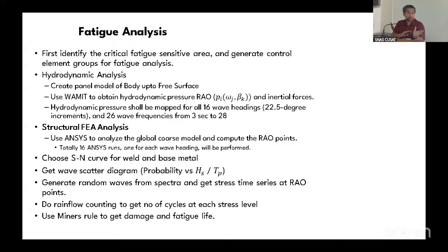Because if you're going to run a time series fatigue analysis for the scatter diagram, that's a lot of runs. And of course, for wind turbines, the number of load cases is humongous, because you have that extra wind part compared to oil and gas platforms. So you have a lot of load cases, a thousand plus.